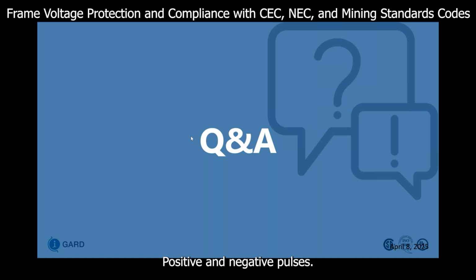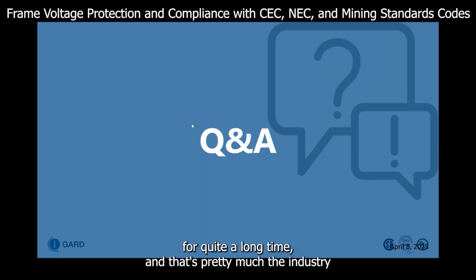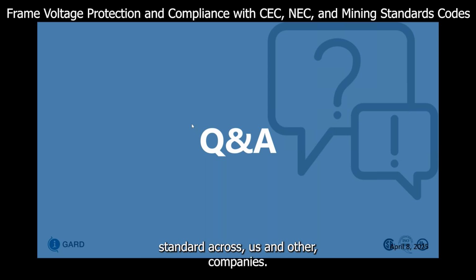What is the voltage used for the pilot wire test? Positive and negative pulses? Is it intrinsically safe? We have two different Zeners that we utilize, which is a 6-volt Zener and a 12-volt Zener. So it's been used for quite a long time, and that's pretty much the industry standard across us and other companies. So I would say that it's a tried method.